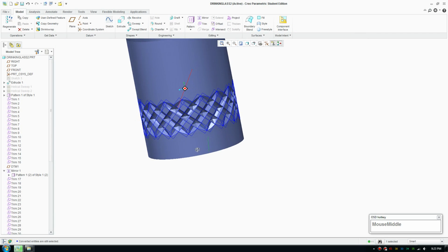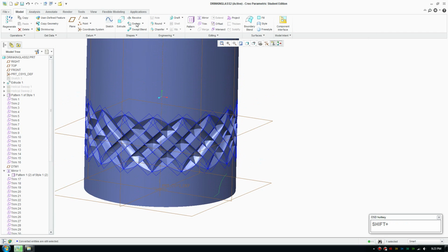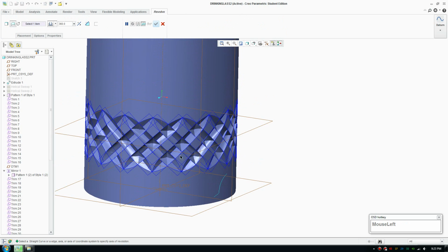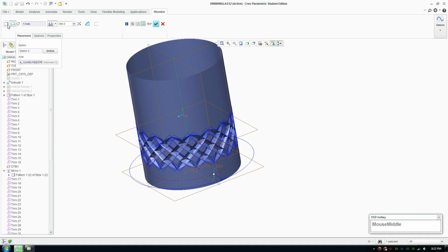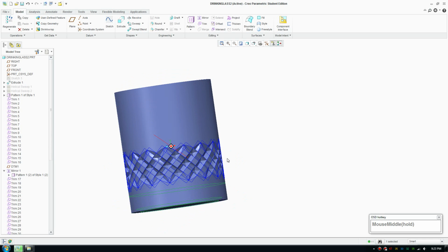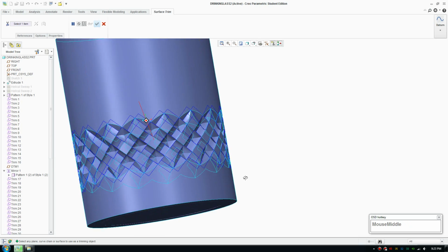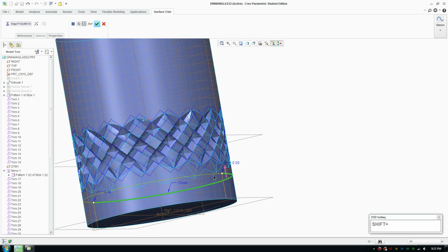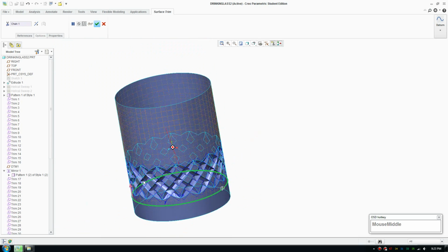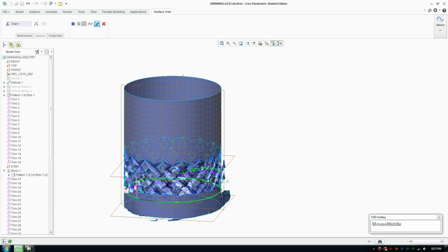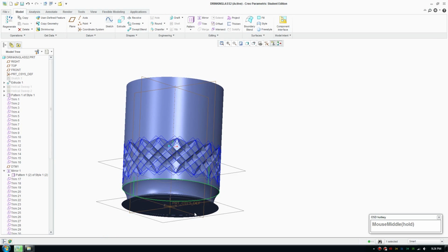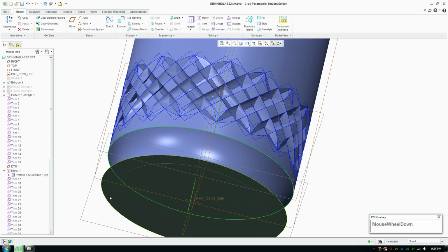That's pretty good, and I'll go ahead and create a revolve, only as a surface, and I'm going to select the axis, which is the middle, and instead of a 3D making a surface, so I can trim the rest out. So it creates a surface on the bottom, and I'll select that, and go trim, and now select the edge. Hold shift to select both sides and point the arrow up to keep the surface at the top. So that creates a cut there, and go ahead and trim the bottom as well.